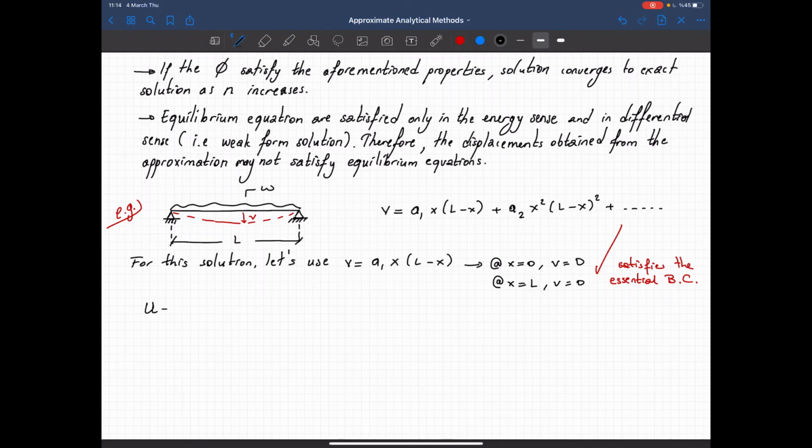So U is equal to, from 0 to L, 1 over 2 M times M over EI dx, right? Force, corresponding deformation, multiply that by 1 over 2, integrate over the whole length, you get your internal energy. That's equal to 1 over 2 from 0 to L. So M is equal to EI times curvature.